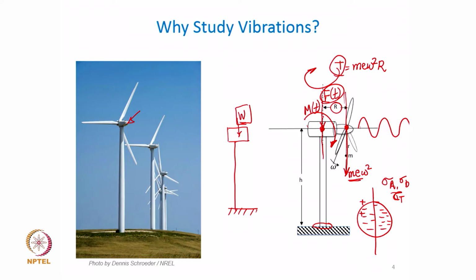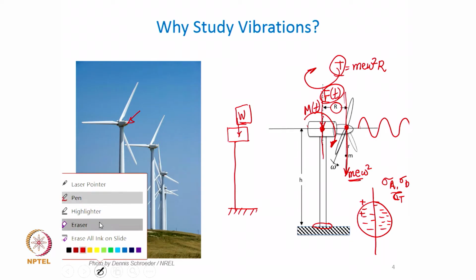So, this is how, migrating from a very basic stress based design, starting from including the static load, the dynamic load will create different kinds of stresses, which is very peculiar to this particular wind turbine nacelle. The design can be made. Now, if you feel that you have taken into account all the kind of influencing parameters to design this column, we need to be very sure whether we are missing anything on this now.